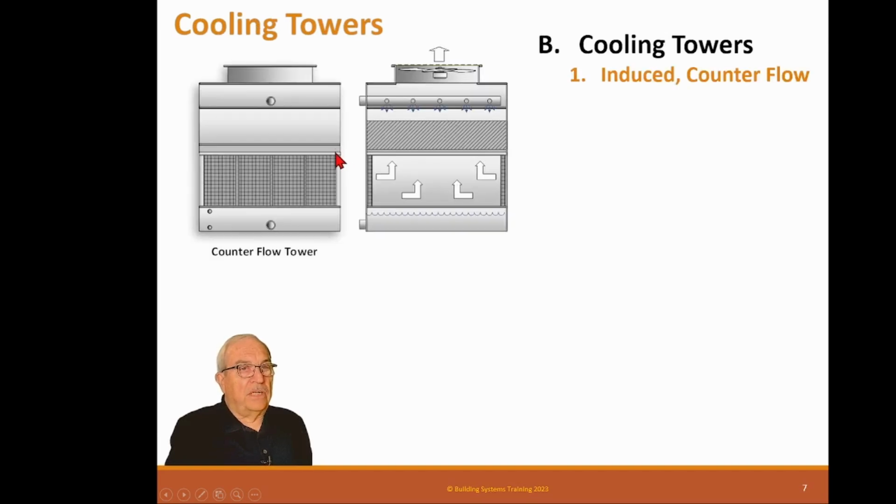All right, cooling towers. Cooling towers come in many different types and shapes and sizes. This is called an induced counterflow, and this is probably the most common one you'll get on HVAC systems. Power plant's a different story, bigger job.